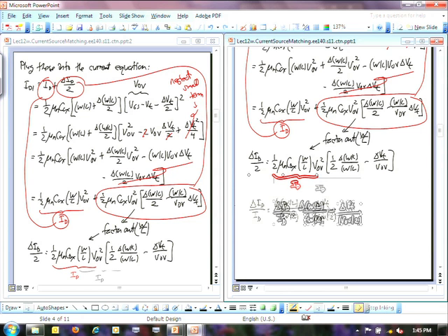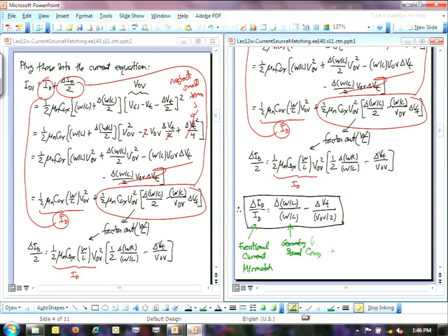Can you design it? Well, no, this is a delta VT, though. This is not the value of VT. This is how different VT is from the desired value. So sometimes it can end up being larger than it, in which case it's positive. Sometimes it can end up being smaller than the target VT. So you don't have control over it because it's a statistic. It's a random thing, from process variations. Does that make sense? So I'm trying to hit VT as 0.7 volts. I might end up with 0.8 volts.